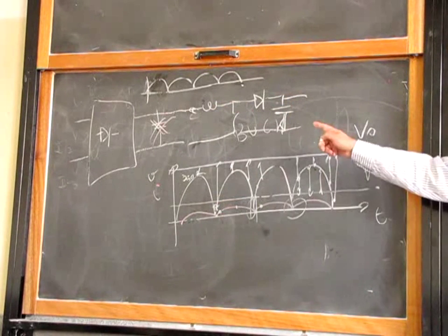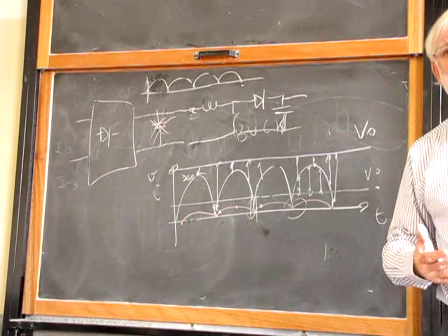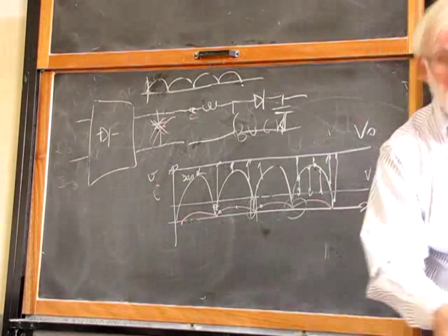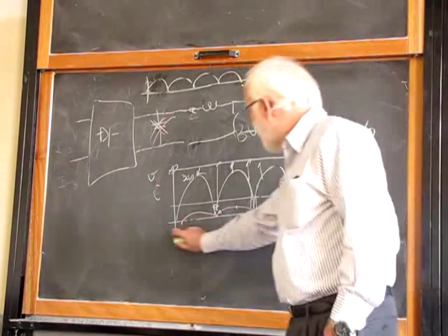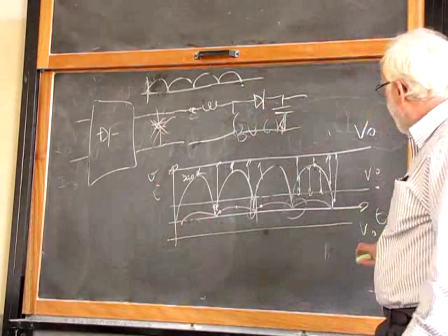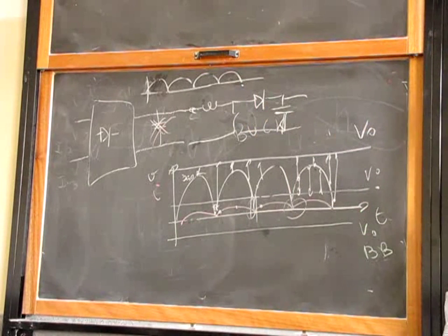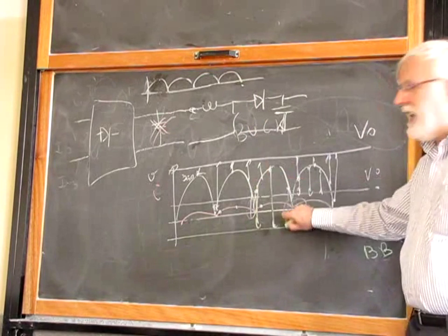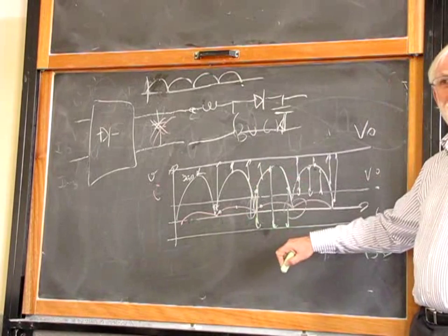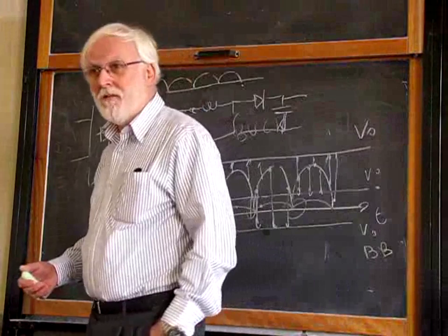What about, that is the second topology we have. What's the third topology we learned? Buck-boost converter has an output voltage that is opposite sign than the input voltage. So I could put here this output voltage for buck-boost. Does it work, buck-boost as PFC? Yes, because any voltage you have over here, you can invert it down to this voltage. So a buck-boost is also a good candidate for PFC converter.